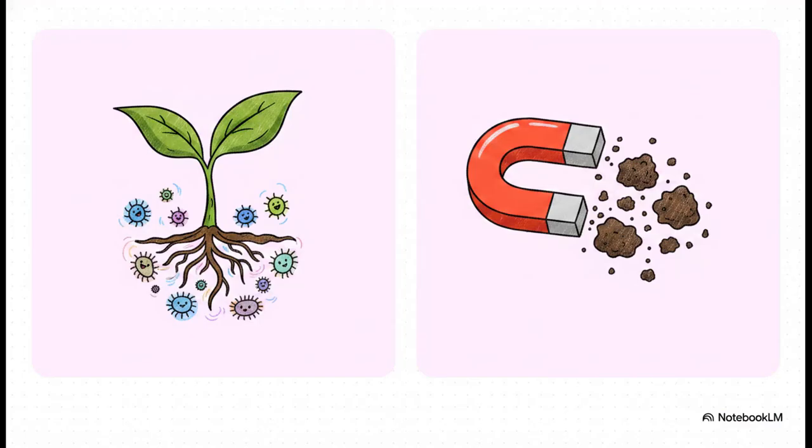Now we have to completely shift our tactical approach for our second suspect. There are two completely different mentalities we have to adopt as water detectives. As you can see, nitrogen control is largely about biological processing and cutting it off at the source. But phosphorus control relies heavily on chemical precipitation and physical traps. Why the stark difference? Because phosphorus loves to grab onto things. It specifically binds tightly to physical particles and sediment in the water. It's a totally different ballgame.